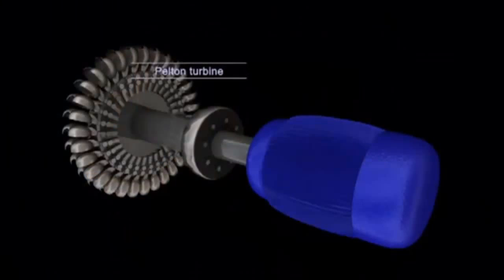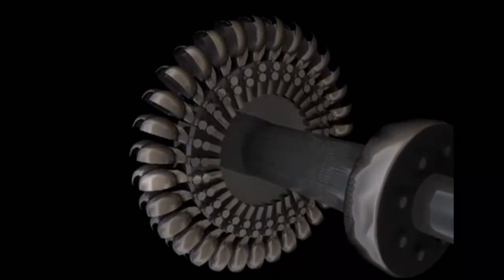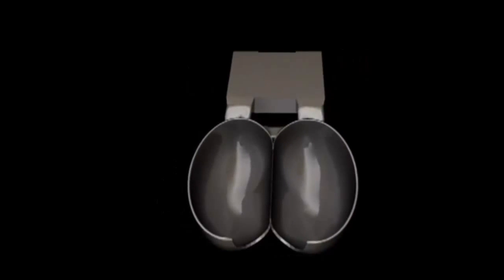The water wheel has long been replaced by the Pelton turbine for several reasons. Because of their clever design, Pelton wheels are far more efficient than water wheels of the past. The rotational movement of the turbine is usually transmitted to a generator, converting kinetic energy into electrical energy. A series of spoon-shaped buckets is mounted around the edge of the Pelton wheel. Buckets are usually cast as one solid piece, which is necessary to avoid damage, such as fatigue failure.